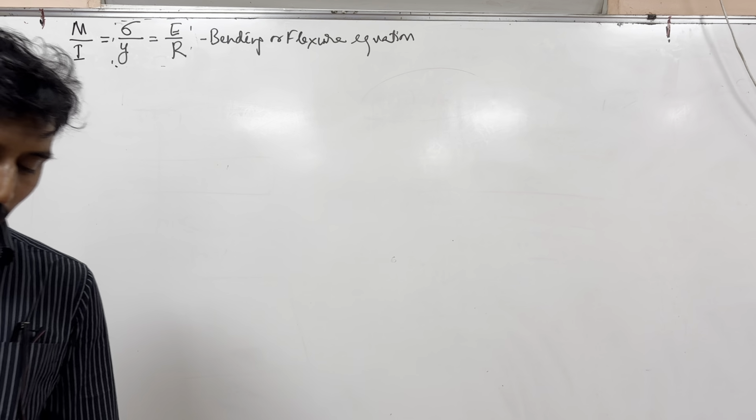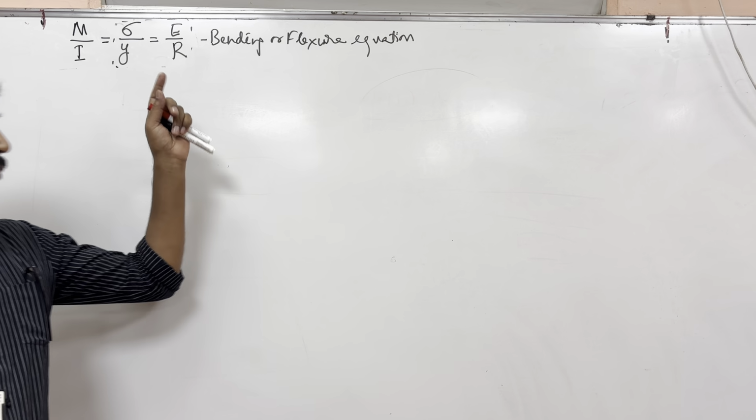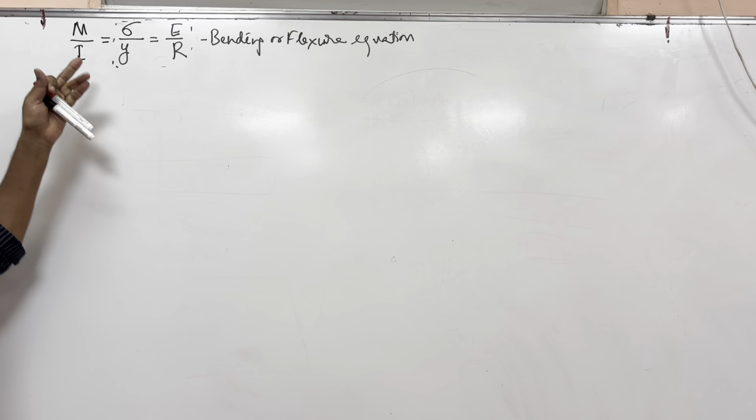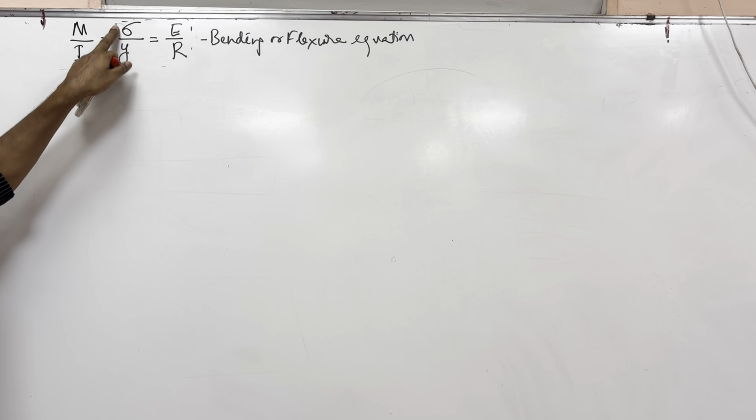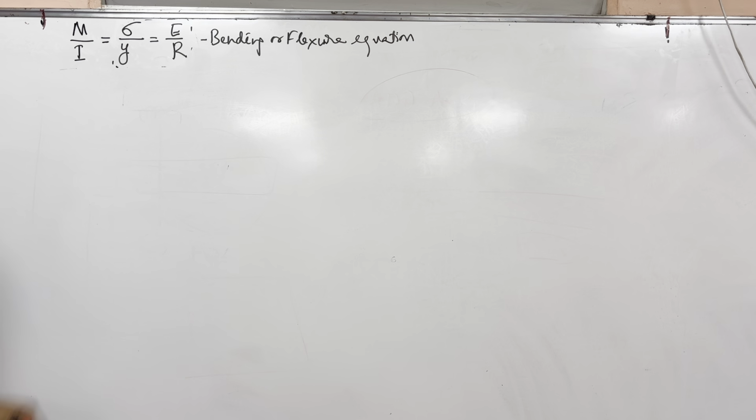Okay, today we'll derive the bending equation, or the flexure equation, which is given by M by I is equal to sigma by y is equal to E by R. I said how you can remember this equation.